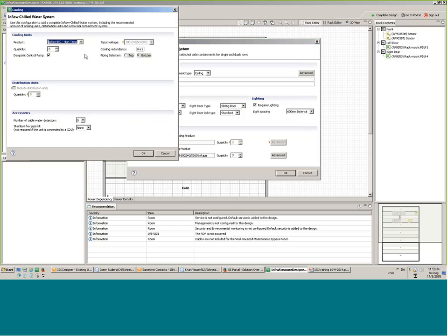always be aware that first of all, high temperature means, of course, you need a high water temperature. You need also your dew point very high. Otherwise, the dew point control pump will run constantly, and that's not something which we want, because it would reduce the delta T on the coil. But always still use the dew point control, because if you have high humidity, at least this dew point control pump can help you. It will not reduce the water in the air, but it can help you that it still runs. So mostly I would have another humidification control in the room.